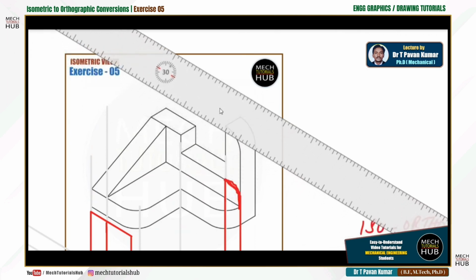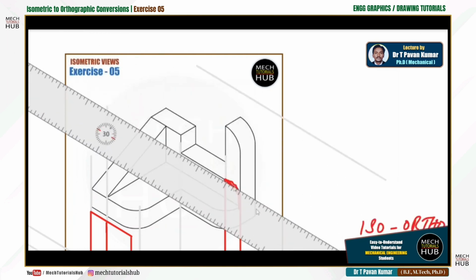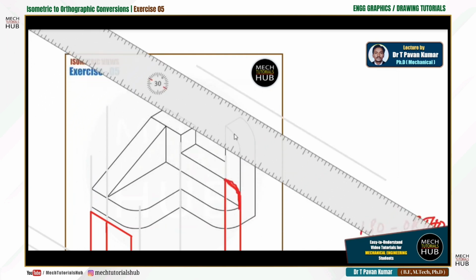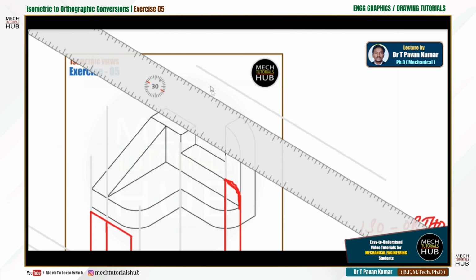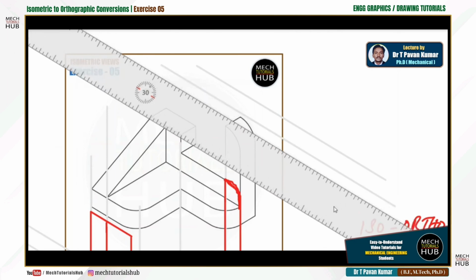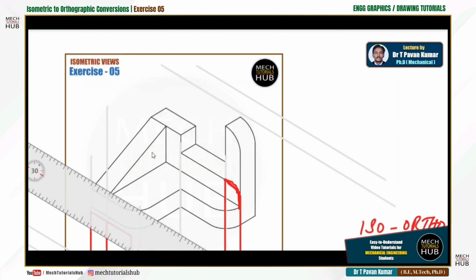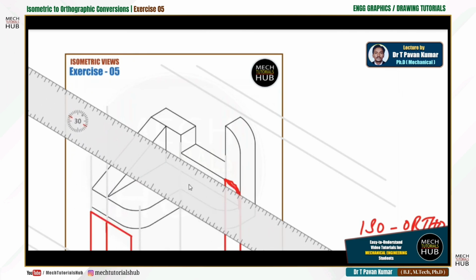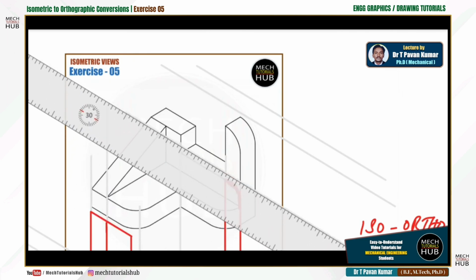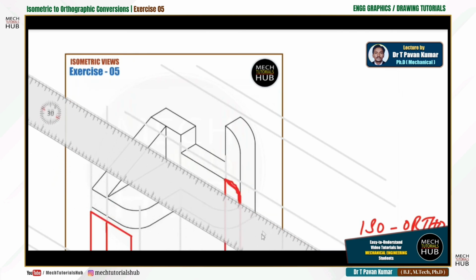Let me draw at some offset distance so that you have clarity about what exactly you are trying to do. That I'll just try to focus on. Let me draw with the help of a construction line. There is a line of infinite distance, and I'm considering this offset distance here with a gap of 10 mm, dropping one more extension, followed by the overall width from one side to the other. Let me draw the overall width as this much, some infinite distance, followed by the profile in between.